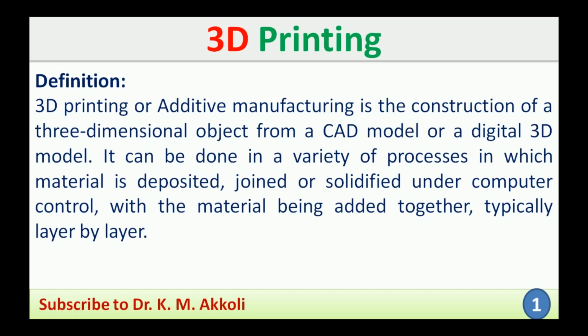Then later, the CAD model prepared on the computer is fed to the 3D printer, where the required material is supplied through various processes, and that material is deposited and joined layer by layer and solidified under computer control. Here it is controlled through a computer only, with the material being added together, typically layer by layer.